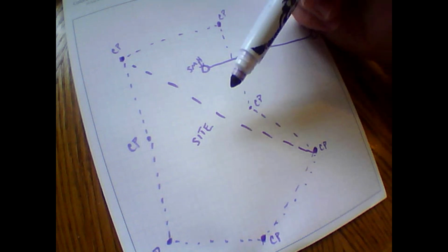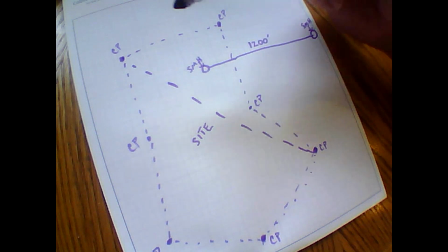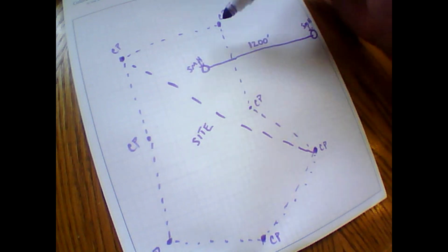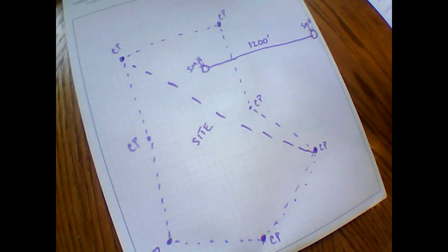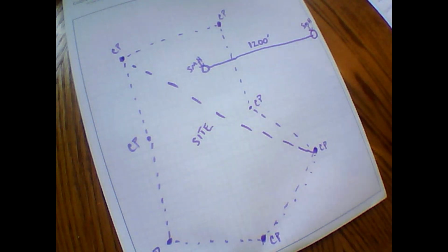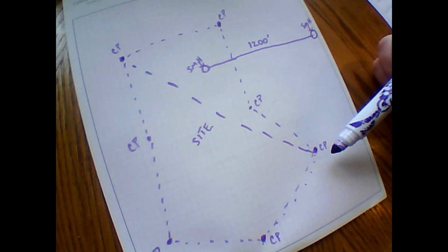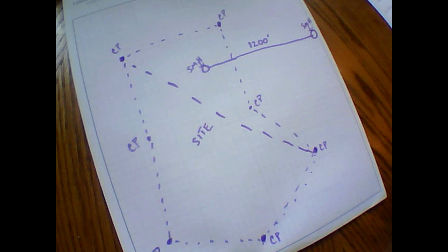You need to be close enough and firm enough that you can stake this entire construction site with confidence. If you miss these things by half a foot, you've got an issue. There's something wrong with the published values. You have to go no projection, no datum, site calibrate to these 2 points. Everything should check. All these published values should check, right?